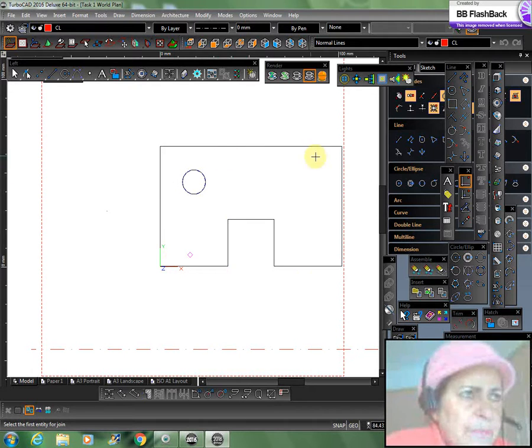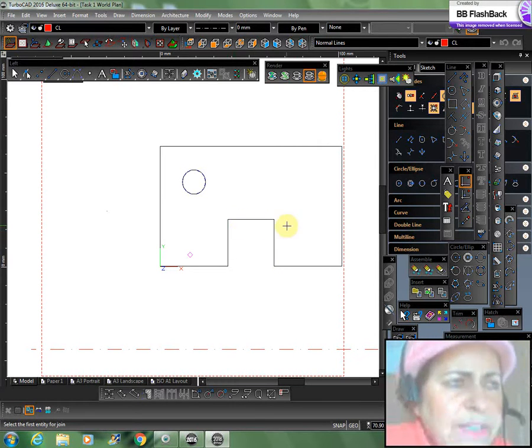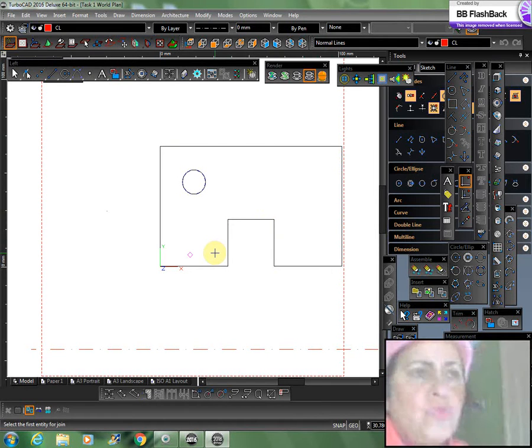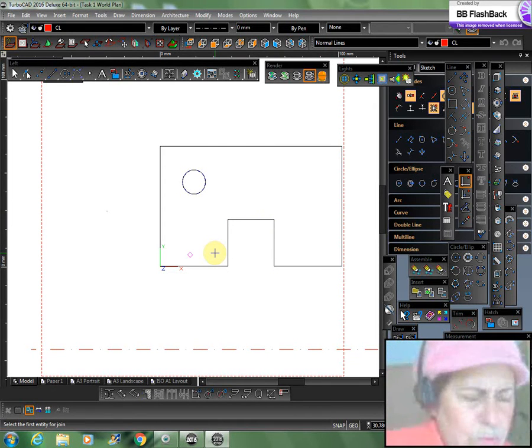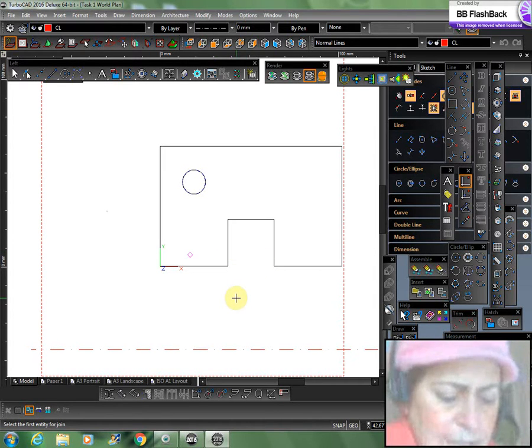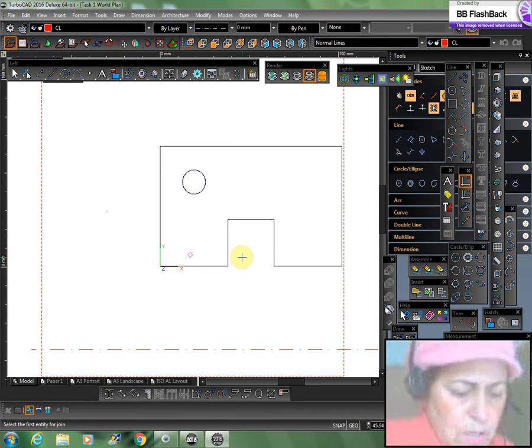around this 2D object that covers all the gaps, because these two lines reach together. There might be a small gap you don't see, and if you have gaps between two lines that intersect, you cannot make a 3D object. You have to close all these perimeters of this object with a polyline to join all the seals and all the holes.